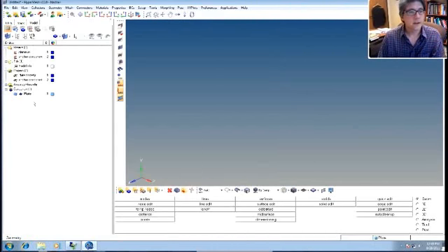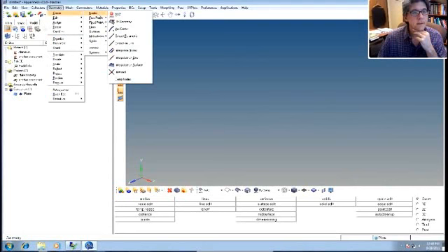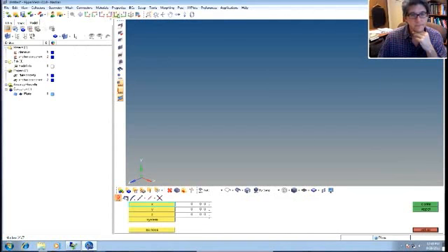Alright, so let's do that. So first thing to check is that the plate component is active, so that means the geometry will go into that collector. Click on the geometry radio button, or we'll pull down stuff from here. So if you pull down from geometry, we're going to create some nodes, and we'll do it by just typing in the XYZ coordinates, all right? So we'll put the first one at 0, 0, 0. So I don't have to change any of these. I just hit create and it's there.